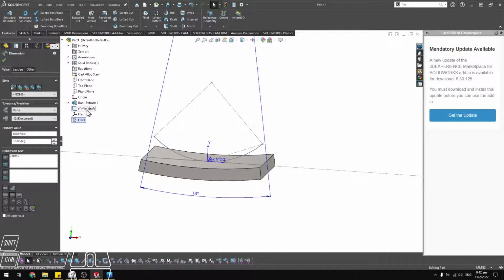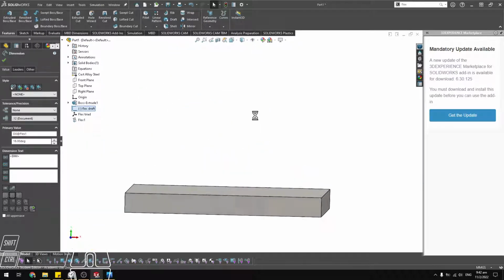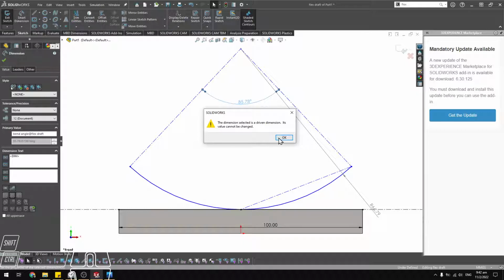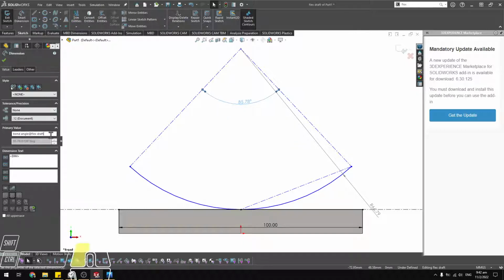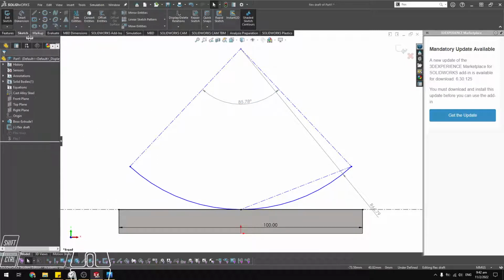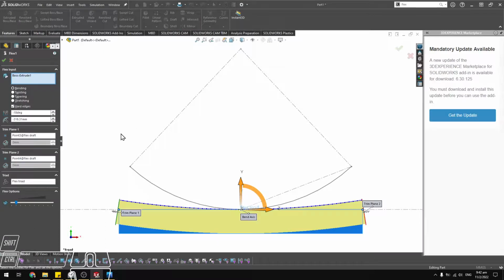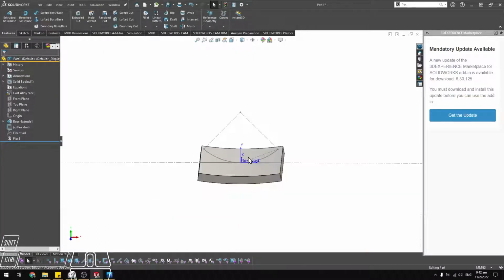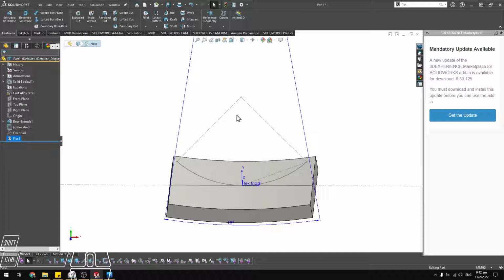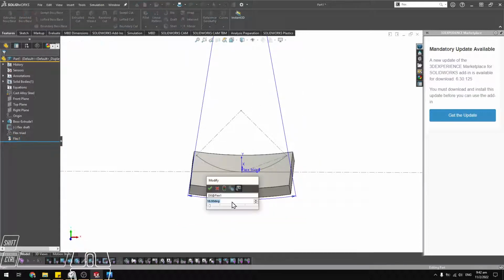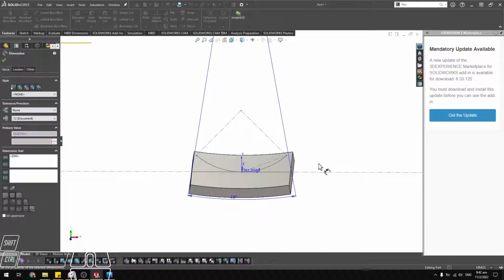Let me take a look. Edit sketch. Double click. Oh, it's bend angle. Okay, so I copy the whole thing. Exit sketch. Go back to flex. Edit feature. Oh, sorry, it's not edit feature. Where is my... Oh, double click this. Double click the 18 degree equals. Open inverted comma. And then select the relations. Enter.